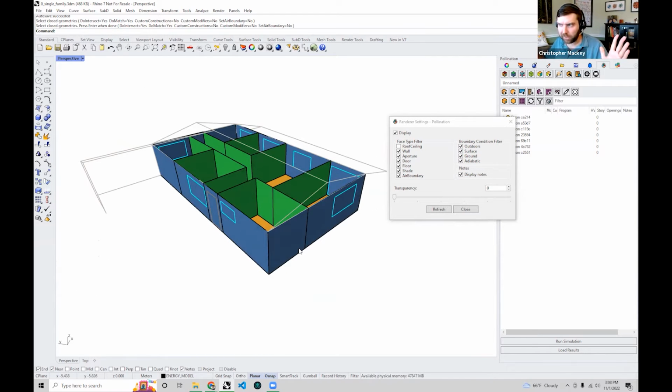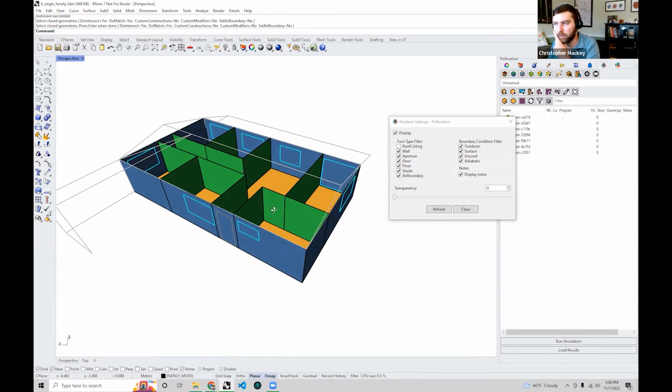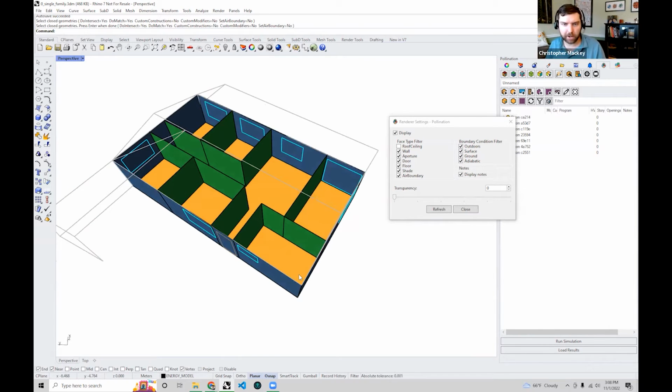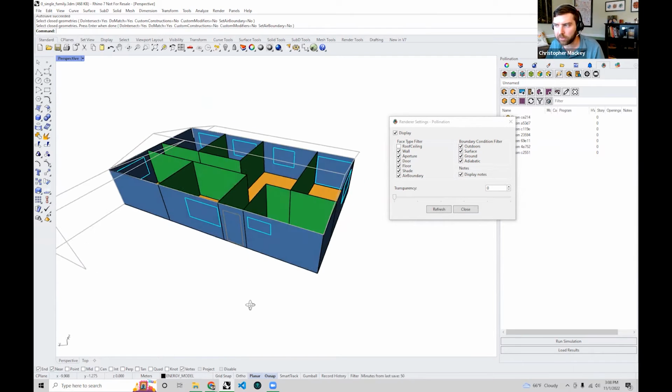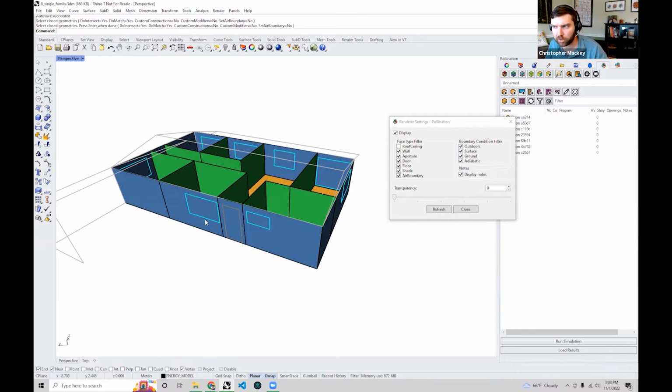All right, cool. So I think at least our interior walls are correct right now, right? We've built this multi-zone model correctly. Does anybody have any other questions, at least on solve adjacency, before we move on to actually assigning these apertures to the model, these windows? Maybe just a quick description of the set air boundary option on there. Oh, sure. Yeah, let's do that actually.